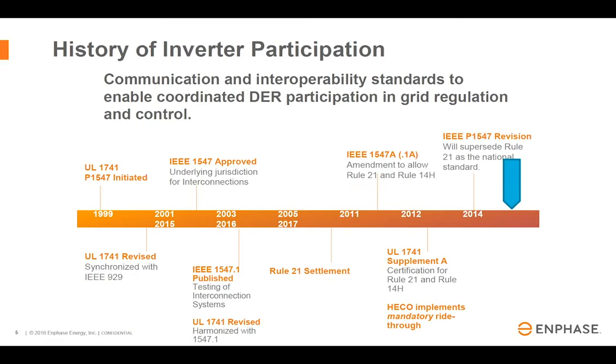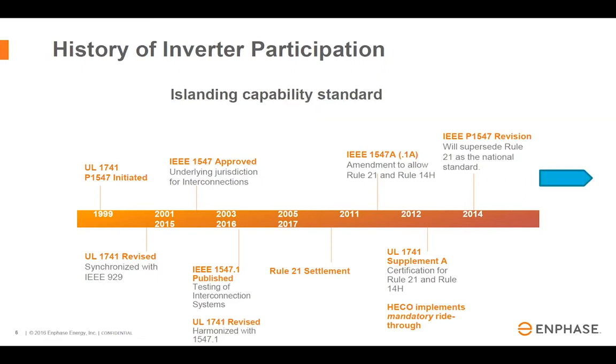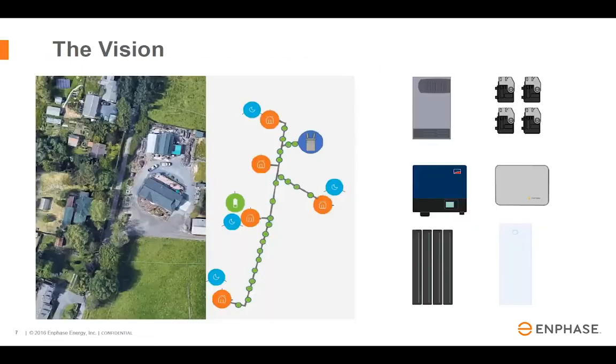But really that's only the first step to realizing this vision of inverter-driven microgrid controls. Because as we've seen, these are basically integrating grid-supporting action into inverters, but still in a grid-following mode, which means they're not designed to form their own grids right off the bat. They're just designed to support a grid that already exists. So what does the future hold? Well, with a bunch of smart people working on the problem, like we have in this room, we can develop standard techniques so that in the future, islanding capability just becomes standard in all inverters.